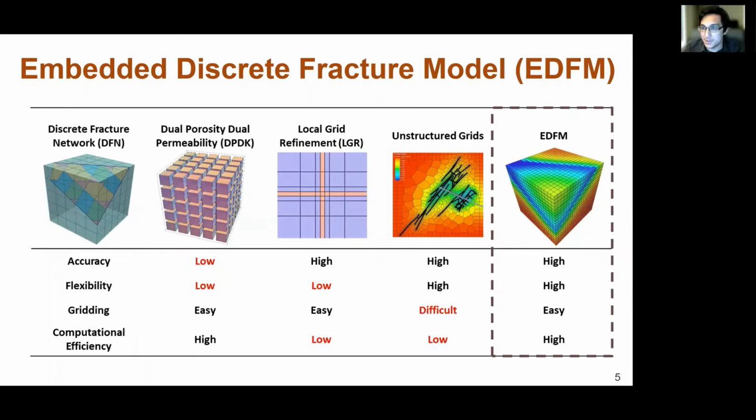So here we have an example of a Cartesian grid. It's a simple grid where we actually have a fracture here in a very complex direction. So we could, for example, use discrete fracture method here exemplified with an unstructured grid, but this would require some grid refinement along the fault. This is very challenging, especially for grid generation tools. Here we have a 2D case, but if we were to go for a 3D case, this would be very, very complicated.